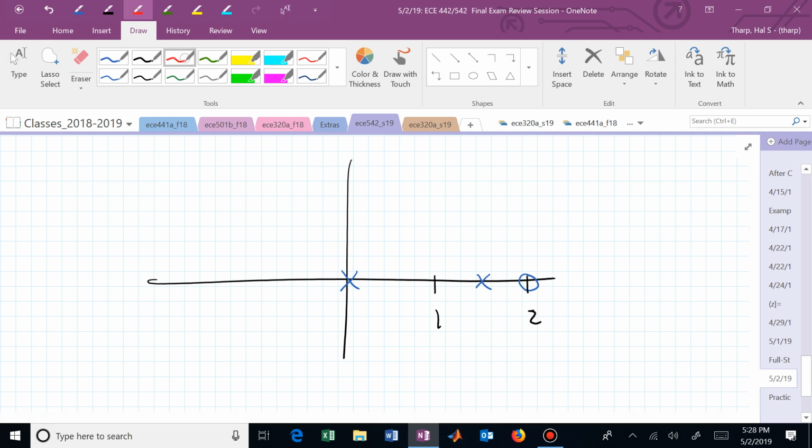Well, one way to possibly get rid of that segment, all of that segment between 1.5 and 2, is to put a 0 in there. But we did keep some root locus there. How many branches does that segment represent? How many branches of the root locus are on that real line segment? Let's say it's 1 3/4 to 2. How many root locus branches?